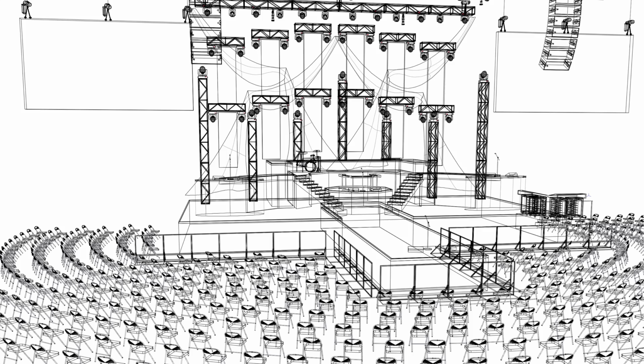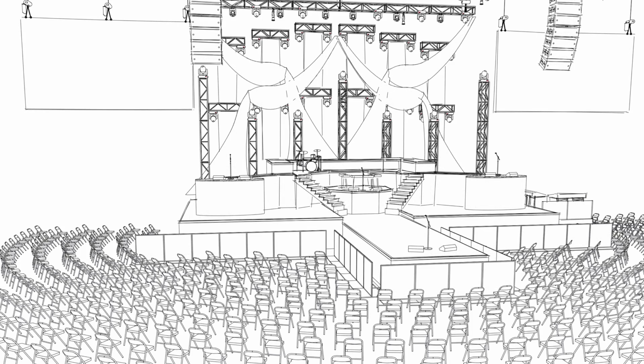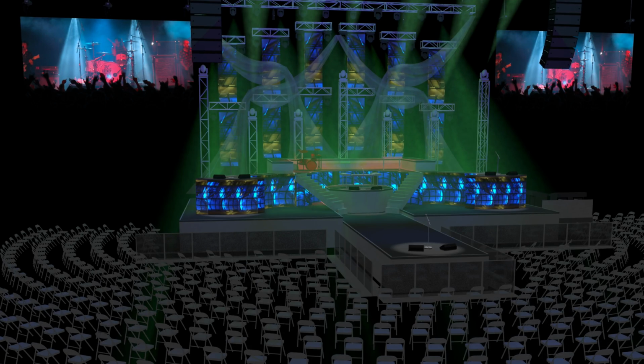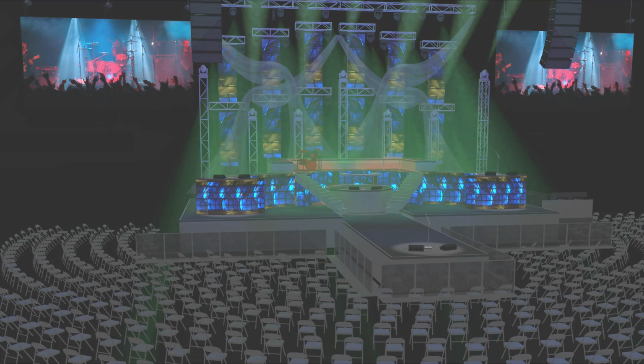Intelligent, controllable, and reportable seating layouts are a breeze within Vectorworks Spotlight. New enhancements to the seating section command provide you with additional layout methods, multiple seat numbering, and graphical controls that are all easily set and modified from the Object Info palette.